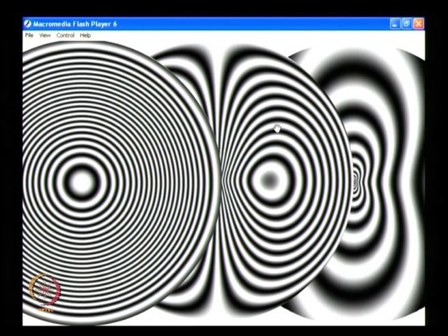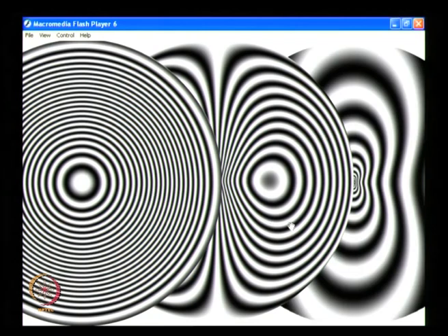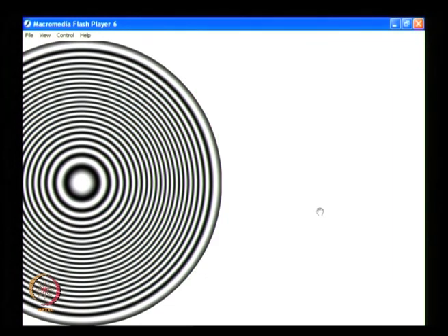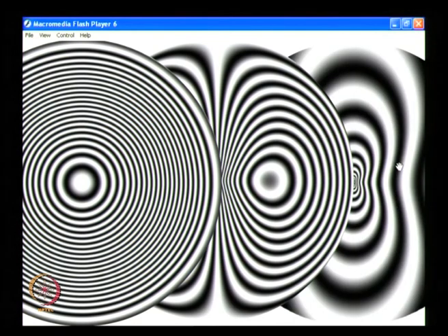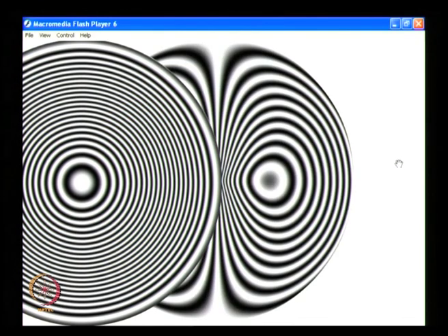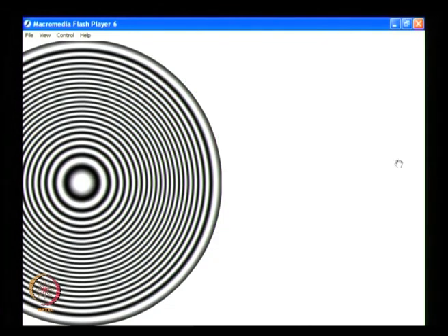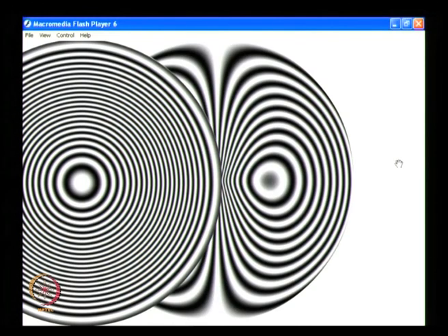And the moment you come here, you see these butterfly fringes, and this you get from shearography. You can also get it from a variation of Moire, and similarly you get these curvature fringes, and curvature fringes, we saw, you could get from shearing interferometry, or from some variation of the Moire technique.